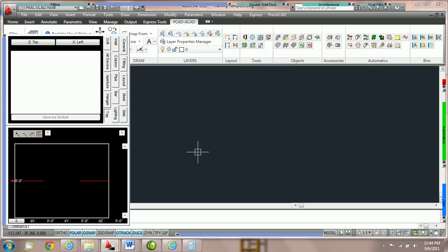In part 2 of the elevation box, we're going to teach you how to build relative bottom and relative top marks. Building relative bottom points is extremely important to make sure that one, all of the tags on your drawing are referenced from the proper reference points, and two, that when you export your drawing, all the entities in your drawing are actually at the right height in the BIM model.